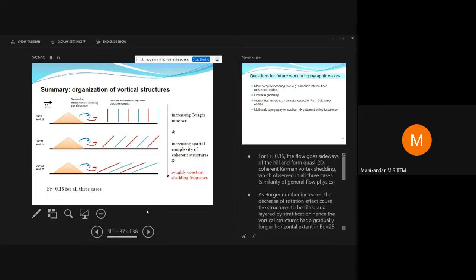The slides that you missed were the result of something called spectral POD, where we are essentially using the fact that we've got certain discrete shedding frequencies, and then we look at the unsteady data time series and extract the structure of those vortices that are being shed. That's a very nice way of isolating the vortex structure.